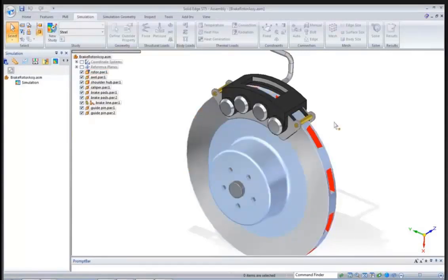So I use that potential energy, which is just the weight of my truck times the height of the hill, and I have to absorb 85% of that with my brakes. Because you've got losses with friction and whatnot, 85% of that energy has to be absorbed by the brakes. I've got 4 brakes, so I divide that by 4. I've got a spreadsheet, I calculate that out, I get about 2,400 watts.